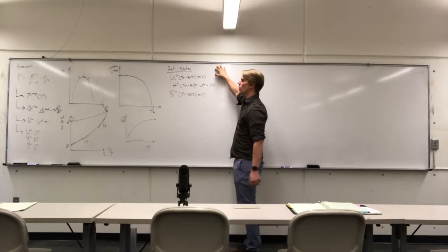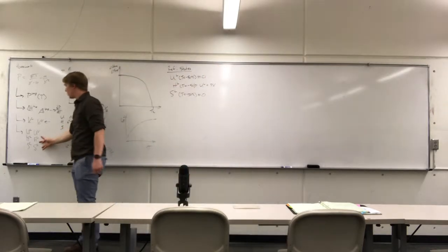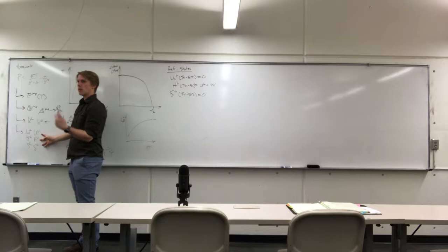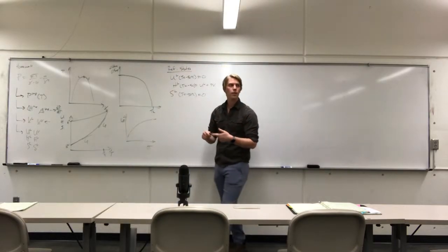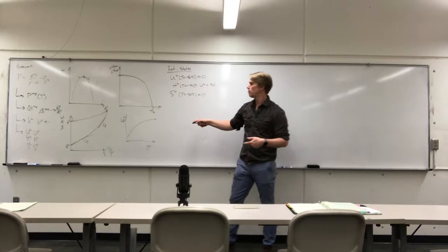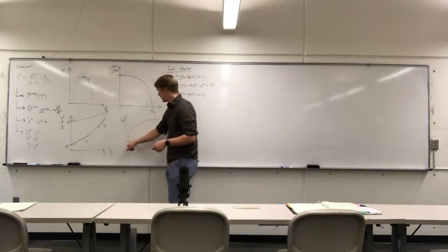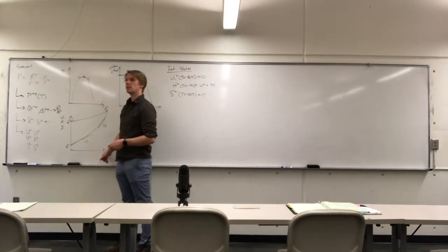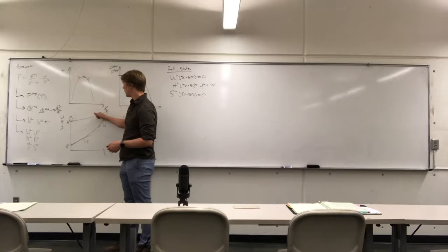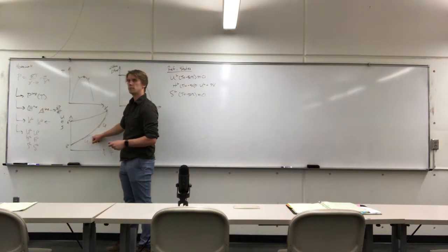So to solve for all of the enthalpy and entropy values, you're going to be using the departure functions that you derived in homework 2. Meaning that you're going to have to couple ideal gas calculations with the departure function calculations to basically go from every temperature of an ideal gas and then pressurizing it, right, to a vapor, that's the departure function, and then using the heat of vaporization to give you information on the liquid. Make sense?